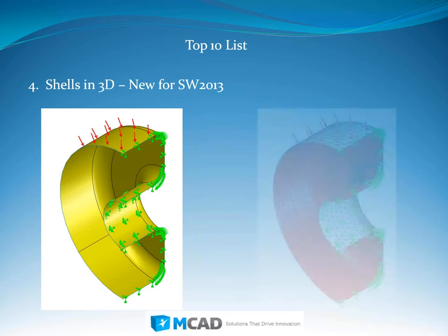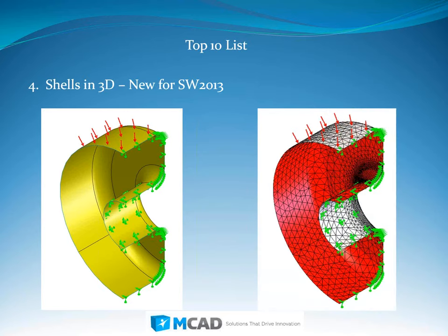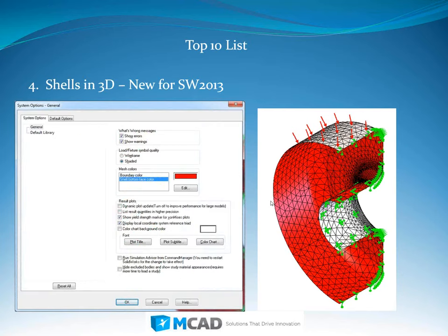Sorry about that. So when we look at the shell representation of the mesh, we'll see a color coding. We get a red surface and a gray surface. What those are related to are what is referred to as the top surface and the bottom surface of the 2-dimensional shell mesh. A little bit more background: the thickness is represented in the shell mesh formulation. It's not explicitly captured with the mesh itself. So we get these 2D elements, and then the thickness is built into the formulation.